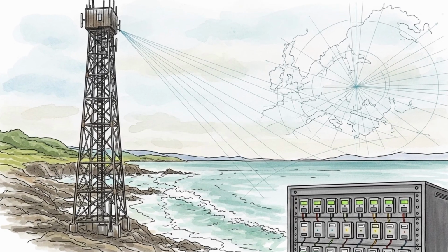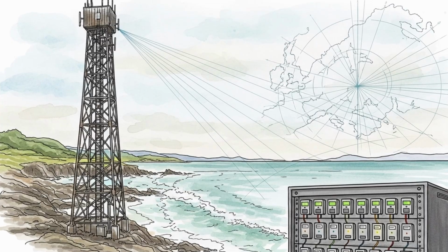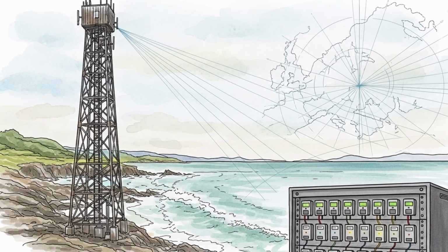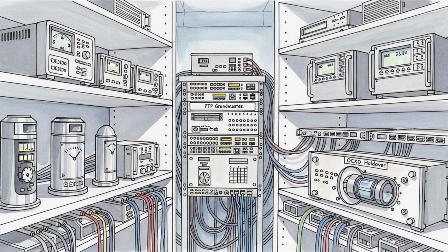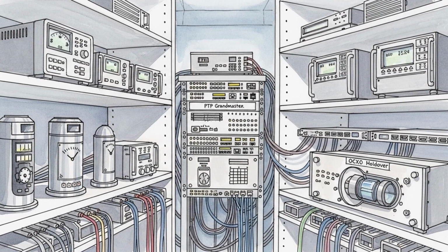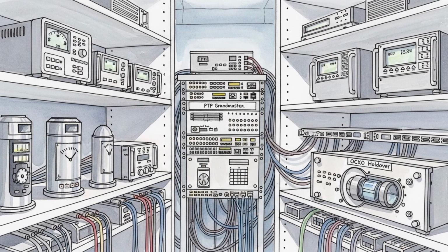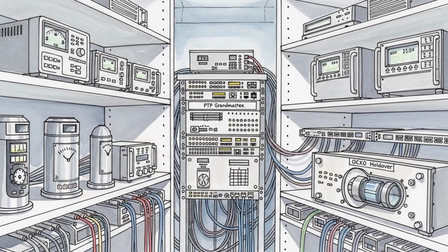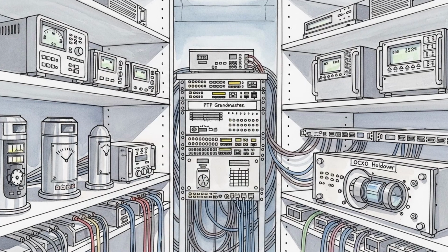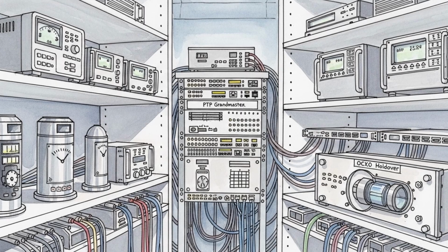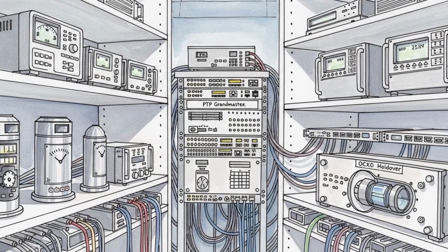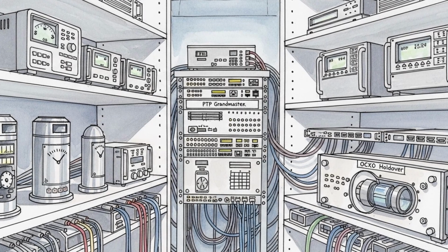Throughout the process, keep transformer loading modest until neutral currents and harmonics return to normal. Document temperatures and alarms for later inspection and testing. Training and drills convert plans into action. Operators rehearse the data displays they will see, the thresholds they will use, and the calls they will make.